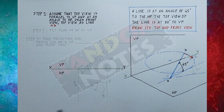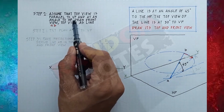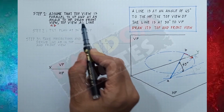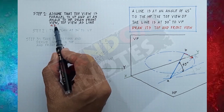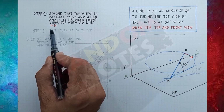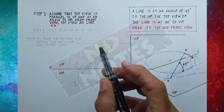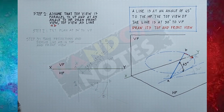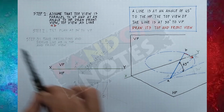So the first step is that we assume that the line is parallel to the vertical plane and at an angle to the horizontal plane. And then we will draw the front view and the top view, and we'll name the line small a, small b. Since it is parallel to the vertical plane, the true length of the line will be visible in the front view.